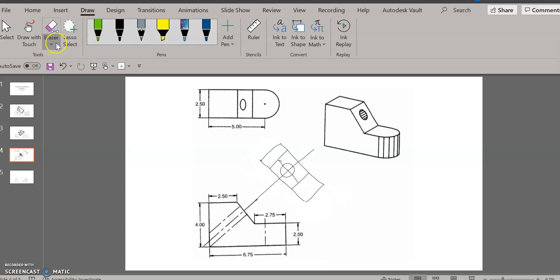Okay, now I'm going to use my small eraser just to clean up my center line so it's a little bit nicer to see. The next step is I need to draw the other surfaces. And by the way, this one here is not supposed to be perpendicular. We need to make sure that that's a rounded edge. See, it's a full radius in the top view, so it's going to be an elliptical shape here.